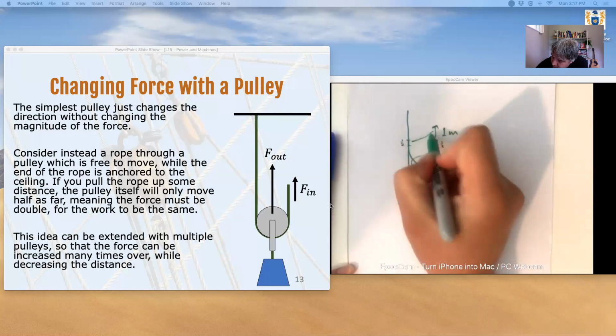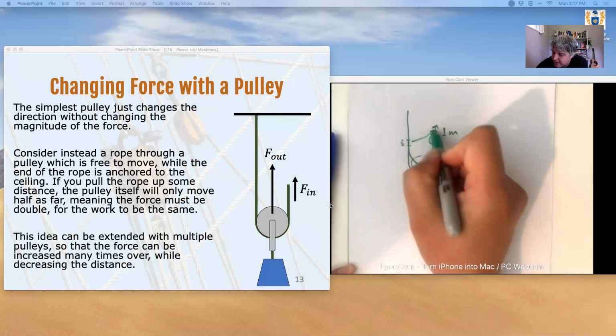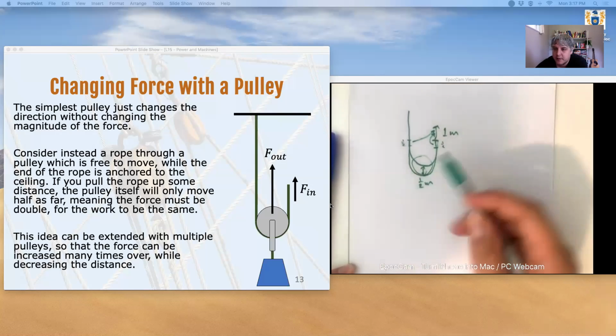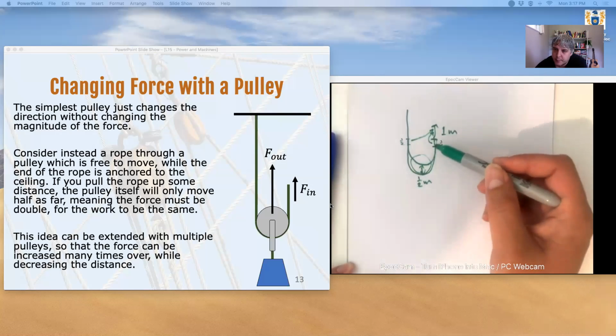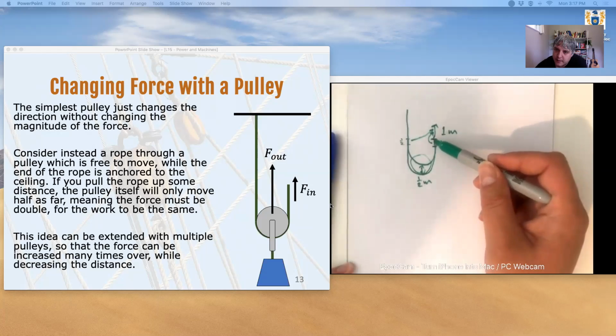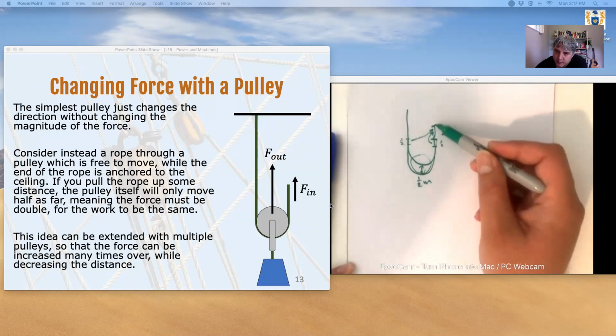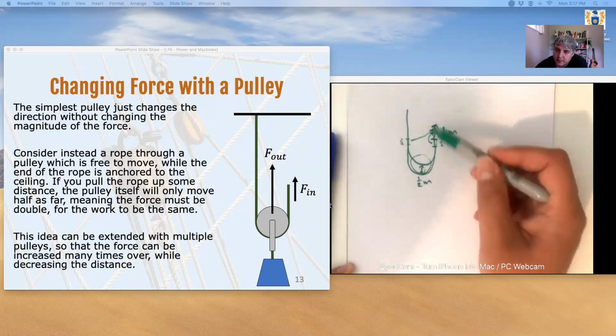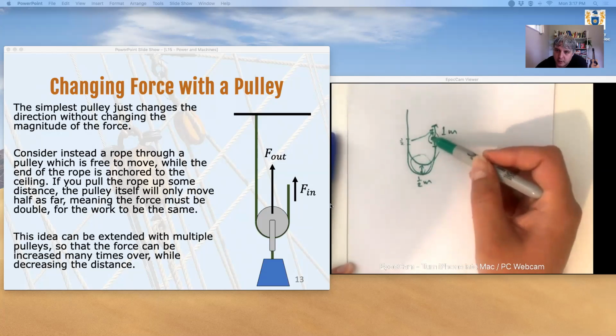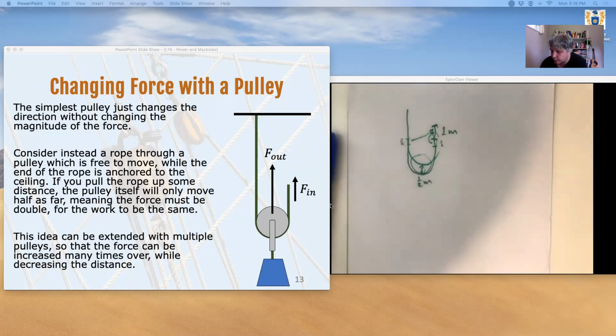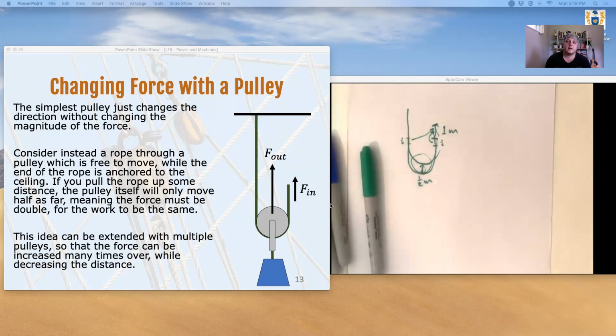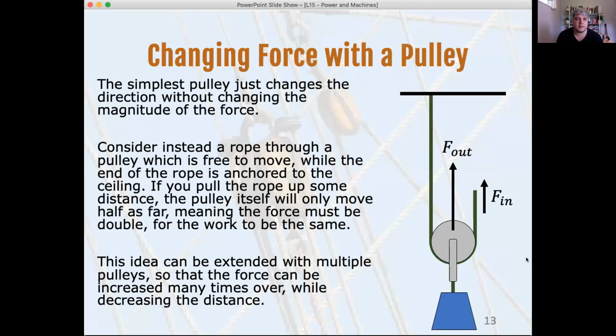It's not actually taking 1/2 meter of rope from here and from here, it's obviously just pulling the rope up, but you can think about it that way, that you've taken 1/2 meter off here and 1/2 meter off here in order to pull this end up 1 meter. So that means that the overall height has gone up by 1/2 meter, even though you pulled the rope by a whole meter. So hopefully that makes sense. Again, just get a pen and paper and draw some sketches and think about it until you're confident that you agree with me on that statement, because it's true.